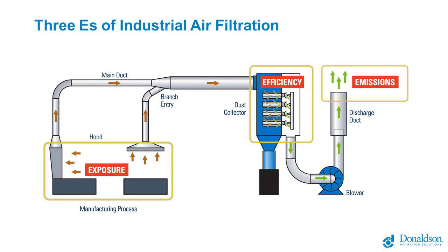For exposure, the goal is to maintain a given air quality level for your employees. There are key variables that can be used to check the status. For example, the airflow that it is designed to meet. Efficiency of the LEV system is the key to achieving either target exposure levels and/or emission values. Trends over time can confirm that you're maintaining stable performance within your LEV system.